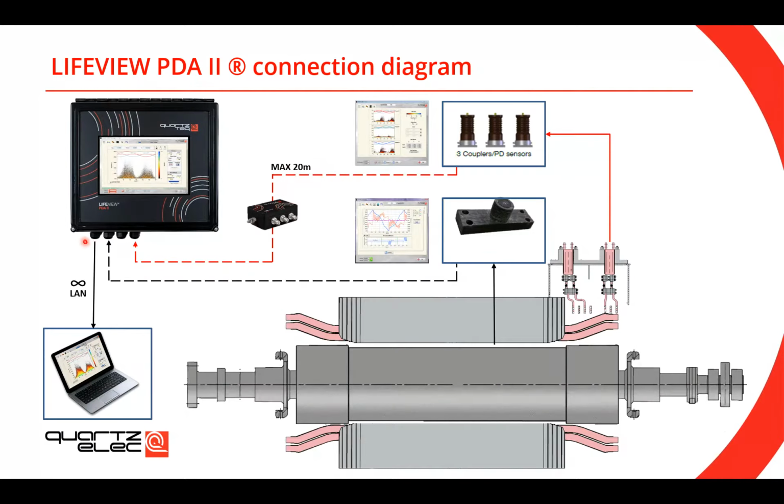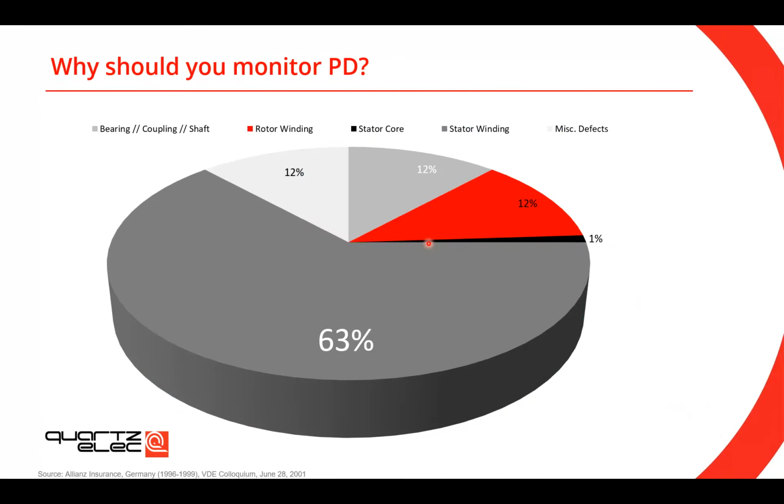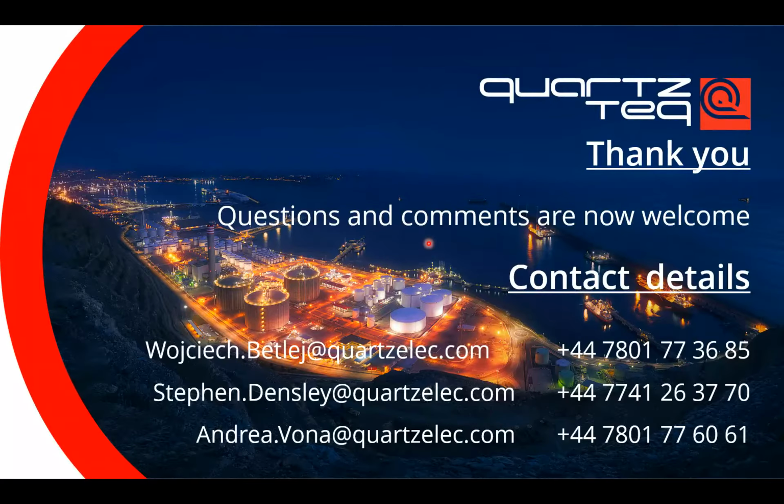If you would then like to further transfer the signal to your control room, for instance, then you would have to use LAN cable or some other protocols. But the BNC cable, the maximum length, let me just repeat, is 20 meters. Thank you. I think that the question might have been asking us to confirm that we have to fit the couplers at the terminals themselves. Oh, well, yes and no.